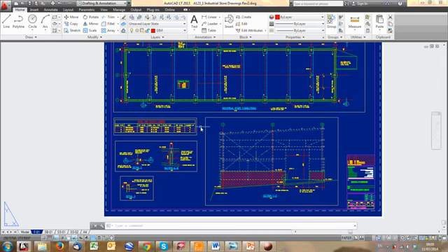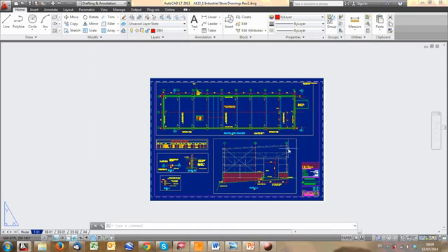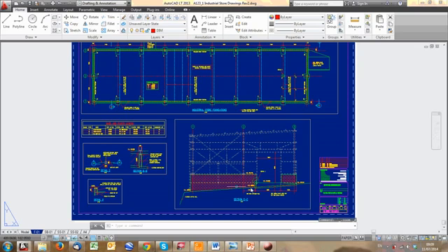You don't have numbers all over the show, and it also means you don't have to change things each time, because when you create it, it's so small, or so big, you can't read it. If we want to now go into a viewport, I'll click on this viewport here. It is now inactive until it's got a thick line around the side. It is locked. If you look in the bottom right corner, it says lock, unlock viewport.